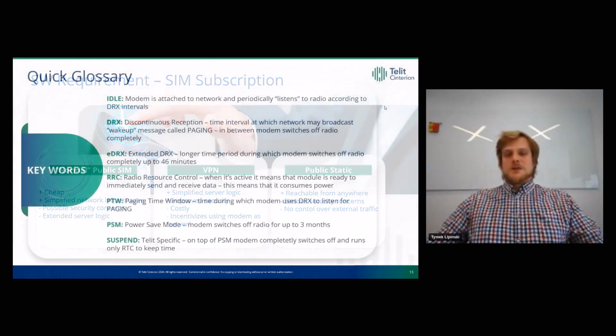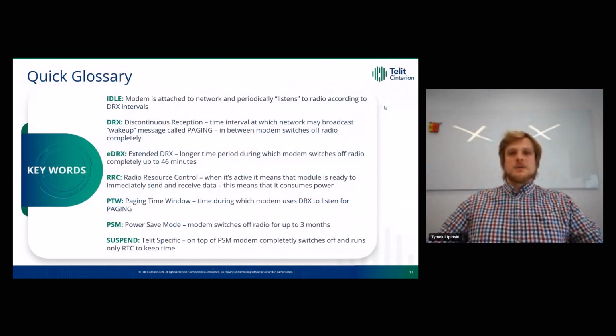Let's jump into a quick glossary of modem-related radio states and how they translate into power consumption. The most popular term and most common one is idle. In general, the modem is attached to the network and it periodically listens, so to say, to radio according to DRX intervals. While in idle, there is no active data exchange between modem and the network, but the modem is registered and ready to send or receive data.